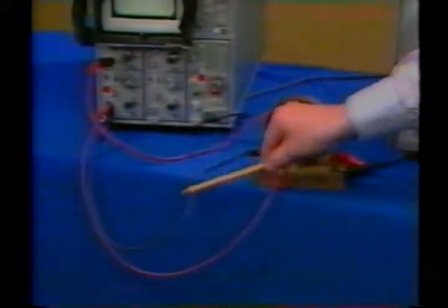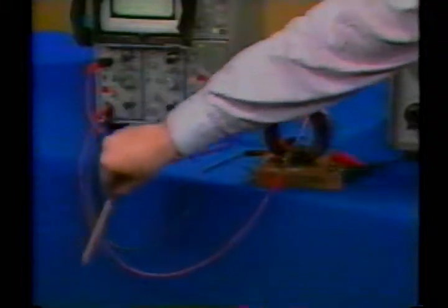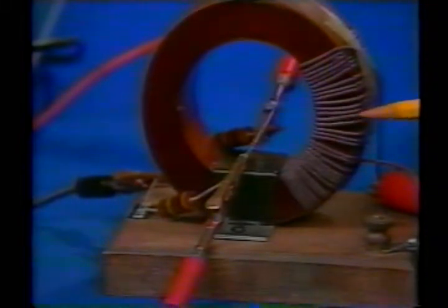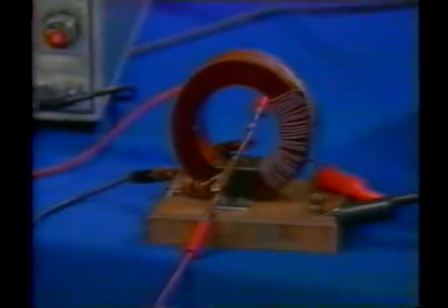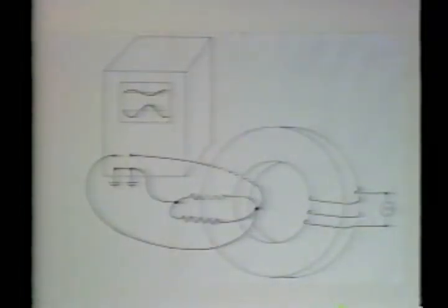Because it is a highly permeable ferrite, the core guides a magnetic flux density B that is much greater than that in the surrounding air. Looped in series around the core are 2 resistors of unequal values. The terminals of these resistors are connected together to form a pair of nodes. One of these nodes is grounded. The other is connected to high impedance oscilloscope inputs through the 2 leads that follow different paths.